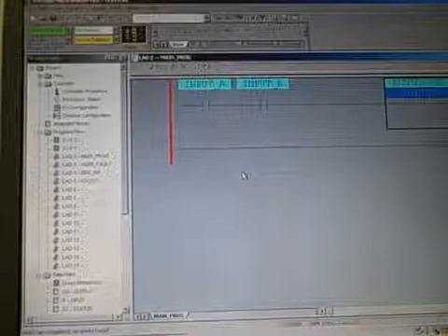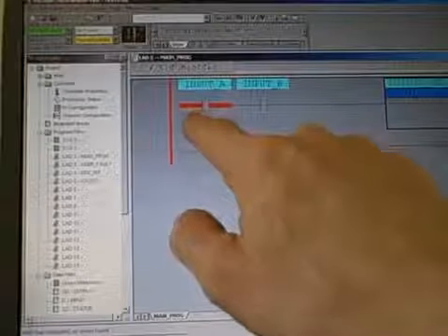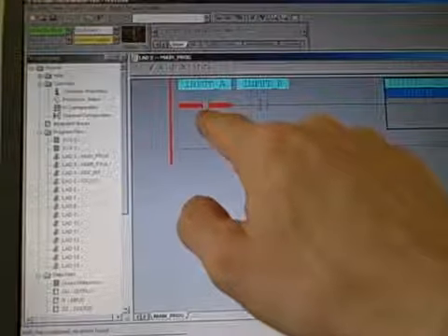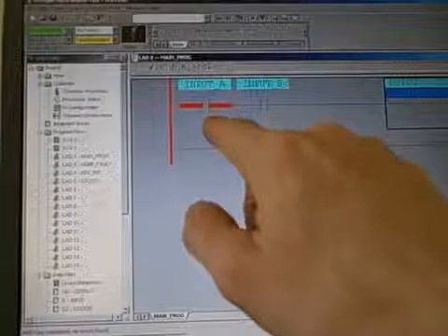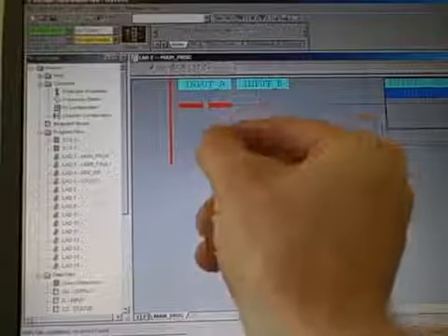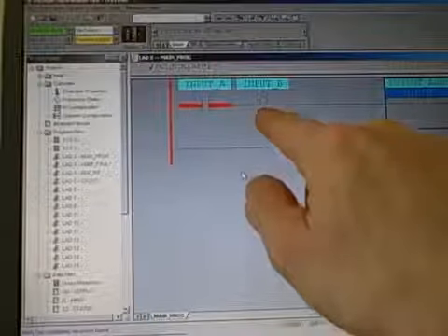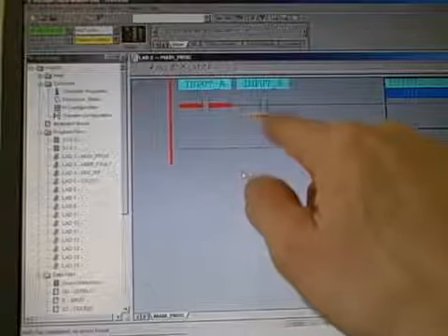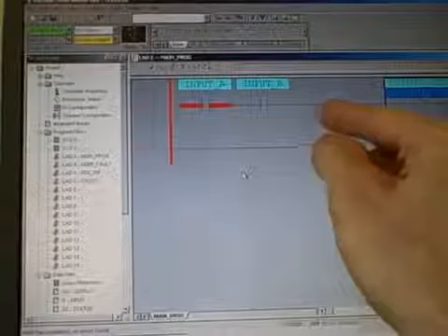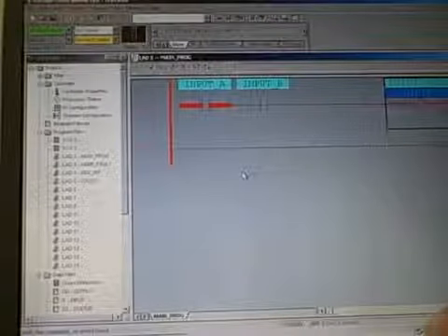If I turn my first input on, input A, that sets the bit for that input channel. The contact reads that bit in the memory of the PLC, and this normally open drawn contact is essentially going to close in an imaginary sense or virtual sense if it sees a 1 status in that bit. This next contact right here, likewise being drawn as a normally open contact, is going to close and pass an imaginary power through if its bit is also in a set or 1 condition.